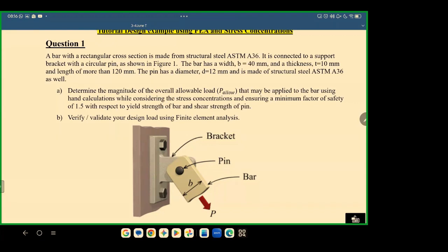to improve the design. So let's say as your initial guess, you have settled with the dimensions that I have given you in the problem, and the material you want to make it out of is ASTM A36. From that, you are going to calculate the allowable load. Then you will see whether the allowable load is based on reality, the kind of load that you want this hanger to support. Is that good enough or not for you? Okay, so that's what we are trying to do.